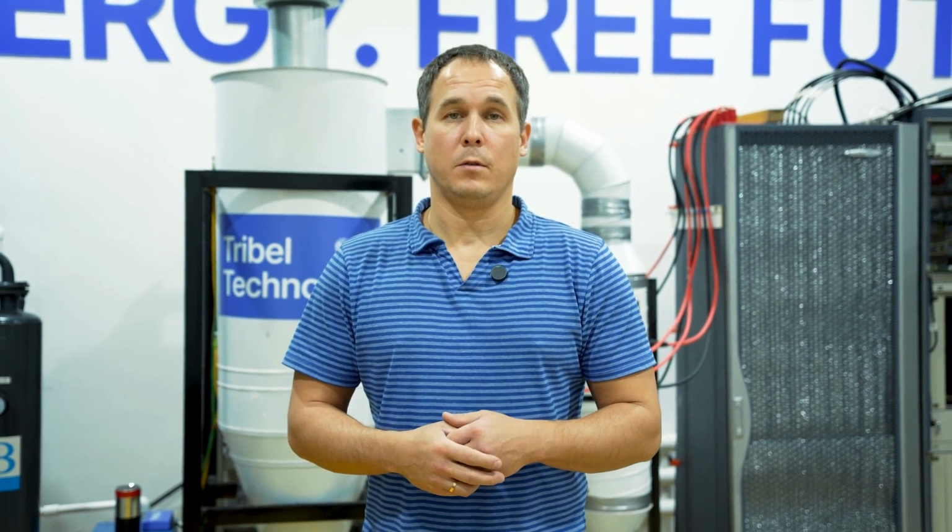First question, why doesn't the compressor start from zero pressure? That is, we have air pumped into the receiver. What is this air pumped in for? This air is absolutely essential to successfully kickstart the power plant when there's no external power source available. So taking that into consideration, we always compress and pump air into the receiver beforehand to at least 0.6 megapascals. That is exactly why the compressor doesn't start from zero pressure.